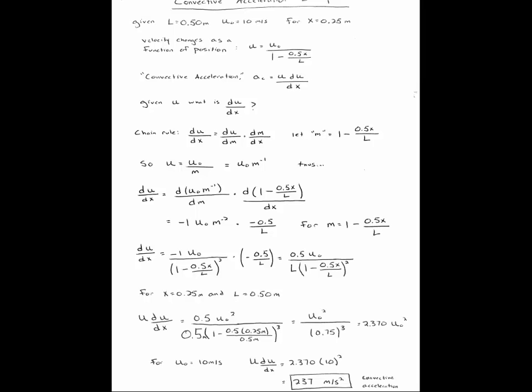Is there a question? Yeah. When we do this, I noticed that we relate it to position and time. What is this relation to area where the diameter of the pipe is? Well, it's the decreasing cross-sectional area that's causing the increase in velocity. In Chapter 5, I'm going to emphasize this, what's called the continuity equation, Q equals VA. What that says is that the flow rate is the velocity times area. And so from that, we can find that the velocity is Q divided by A.